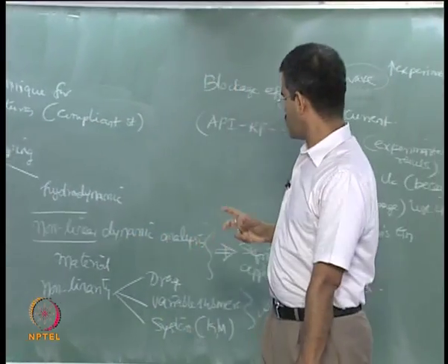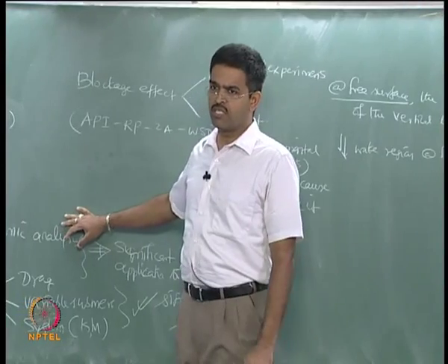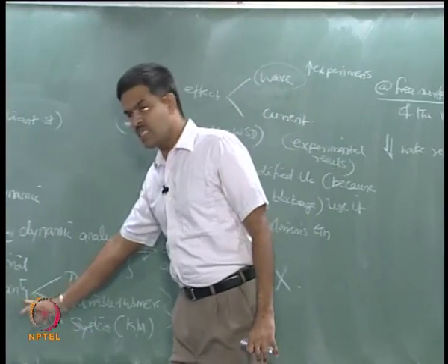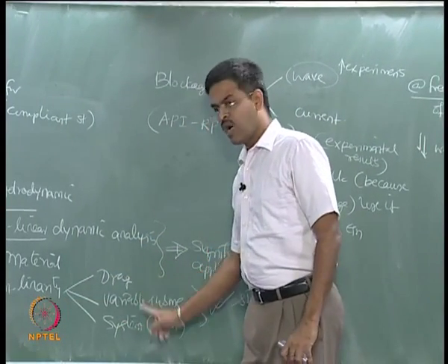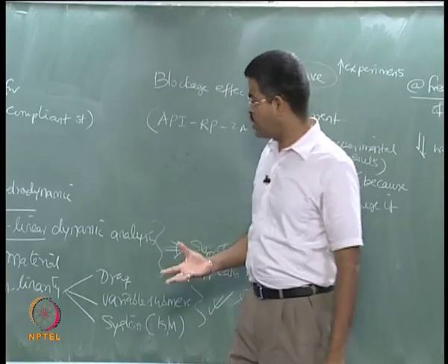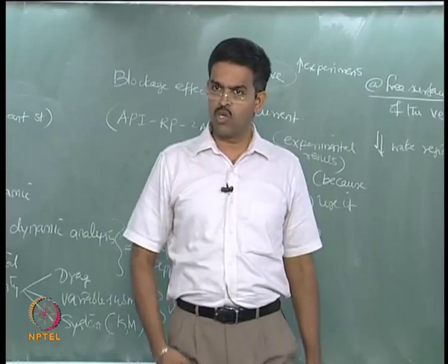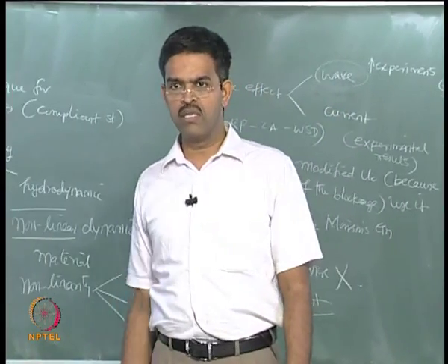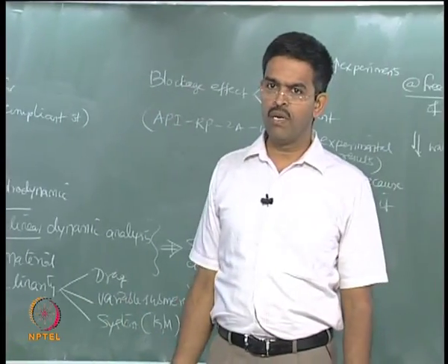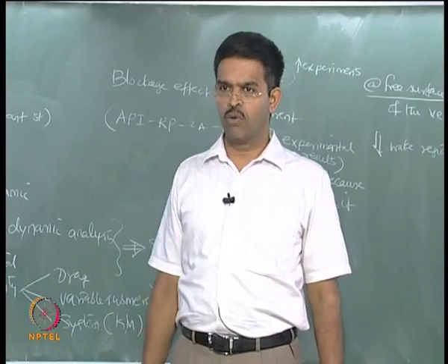Therefore, when we talk about non-linear dynamic analysis, we focus essentially on non-linearity arising from the forcing function or from the system non-linearity, not from the non-linearity arising from the material properties. Of course, it is also present, but we do not look at this in ocean structures. Predominantly and significantly, it will not get reported.